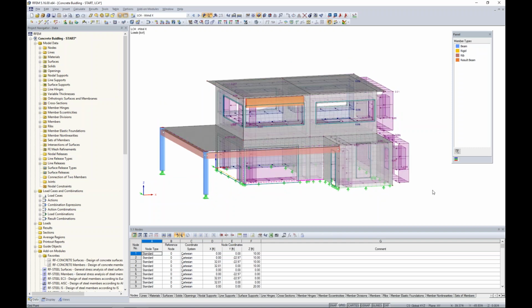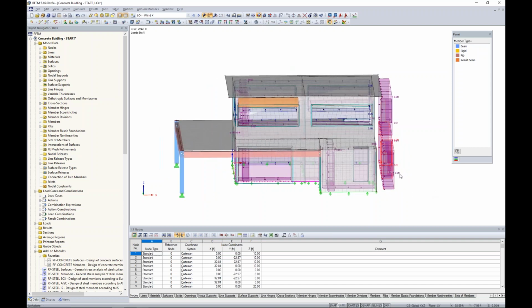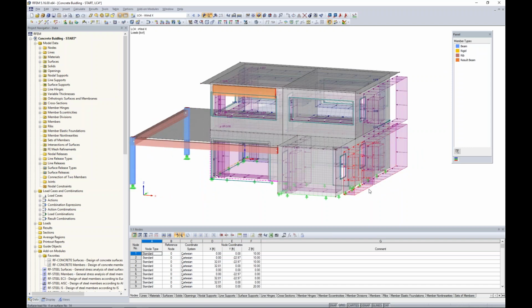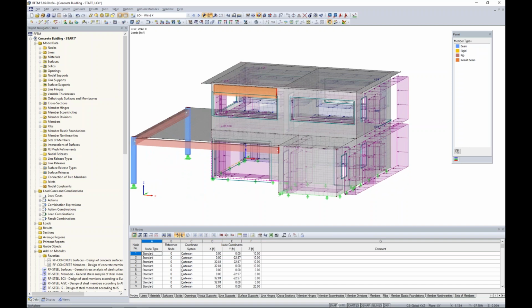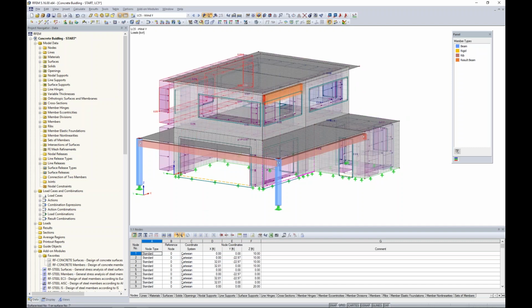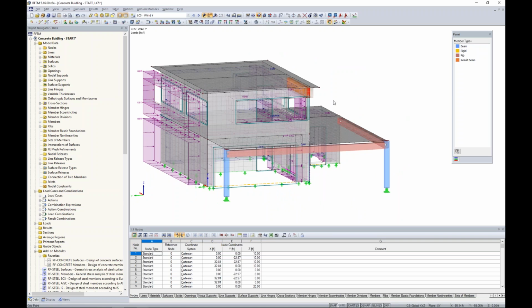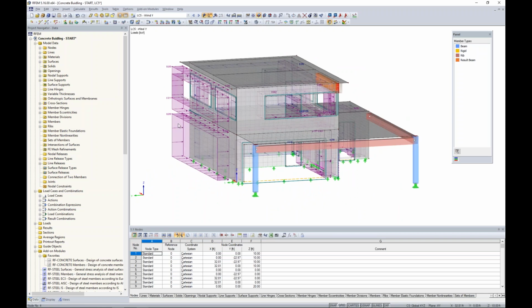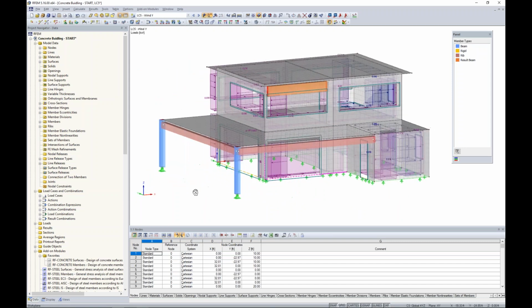Lastly, we have our wind loads. We can see an external pressure being applied in the global X direction, as well as some wind loads, again, all surface loads applied on the inside of our structure as well for an outward pressure. Same concept for wind in the Y direction, except where we're just rotating the directions here 90 degrees. So we have a wind in the global Y direction with the surface loads applied.